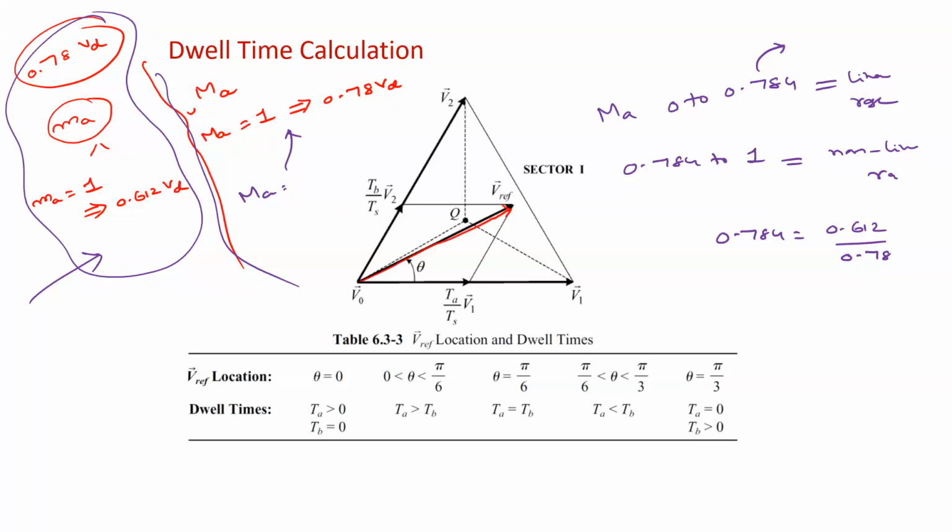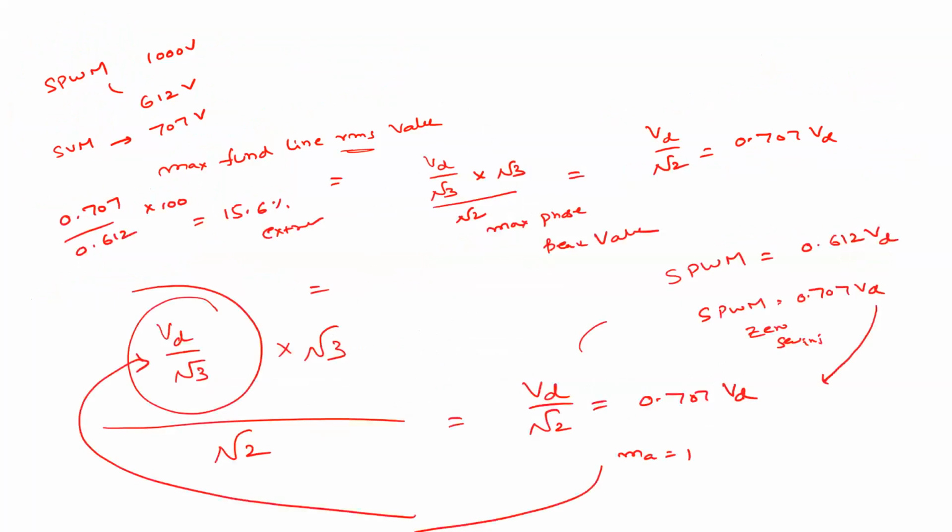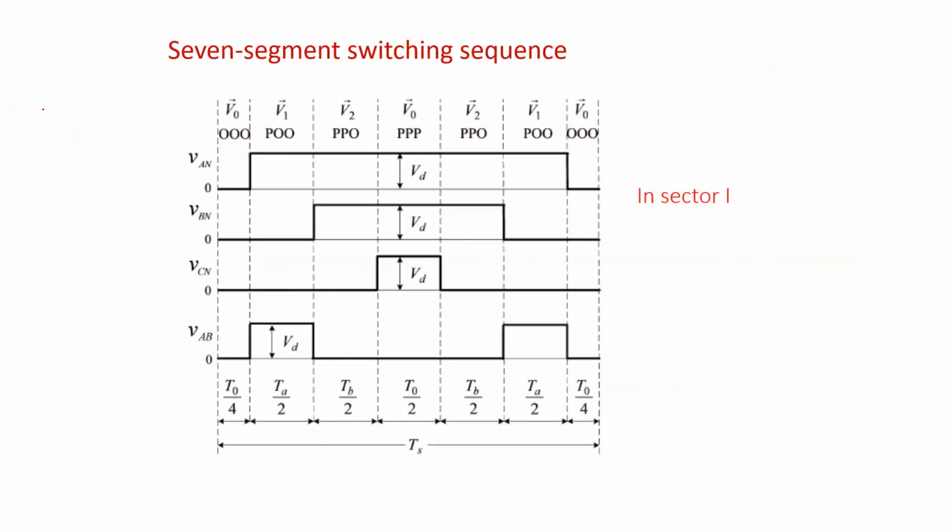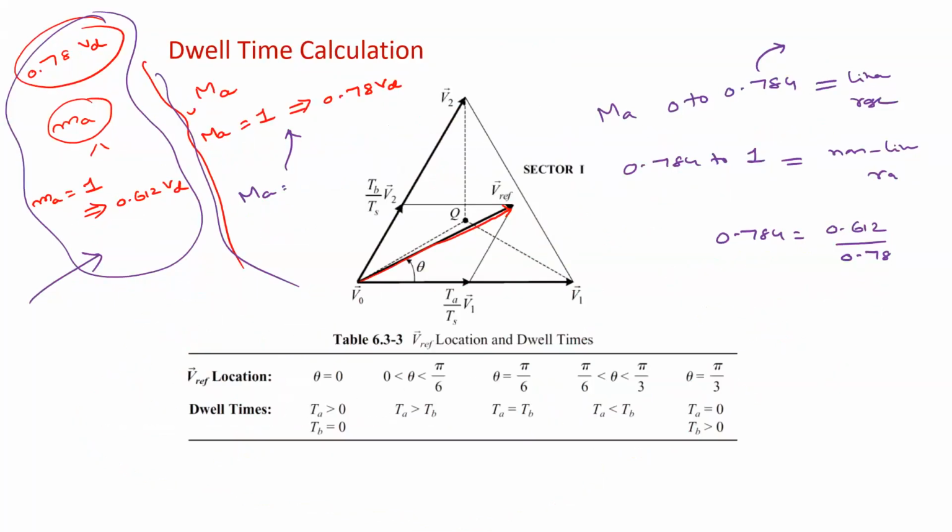Now the things change. Here onwards, the actual space vector modulation implementation technique will vary. How exactly will it vary? We had three times available, so we had TS, which is divided into TA, TB and T0.